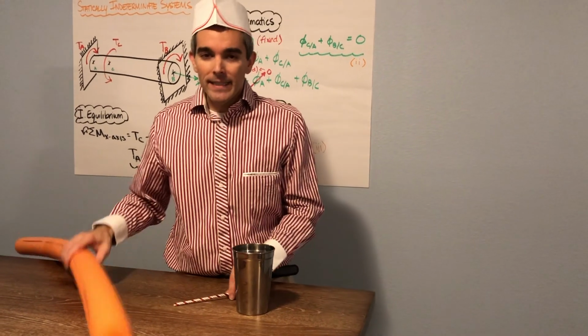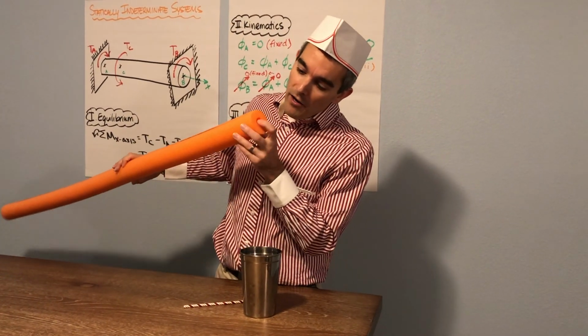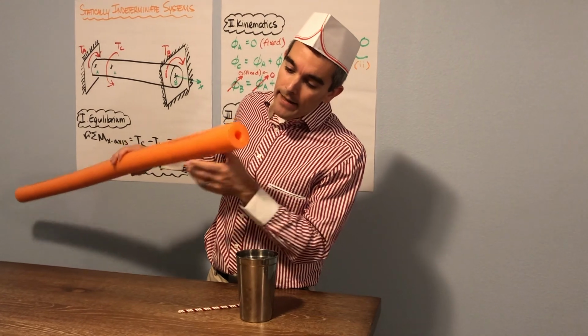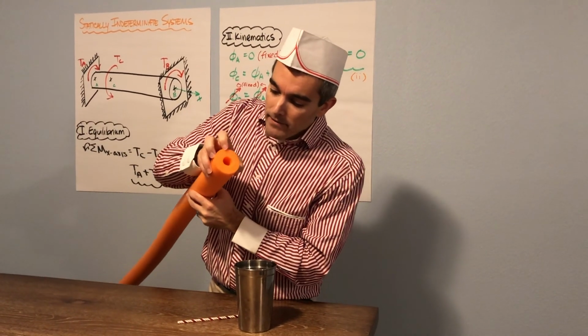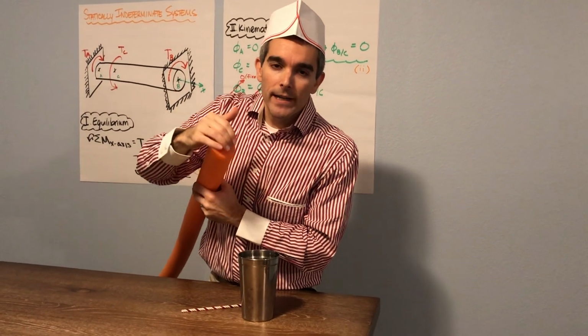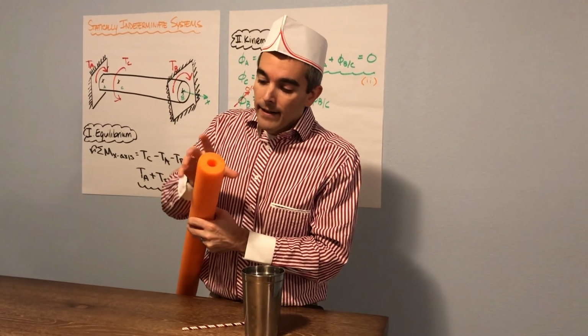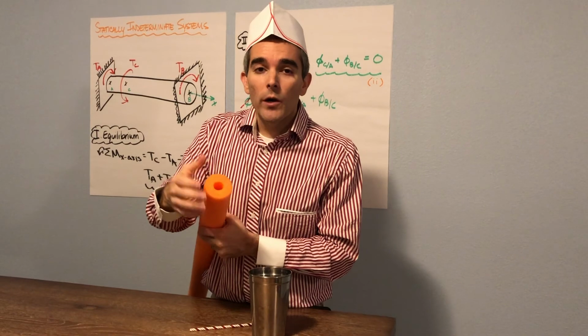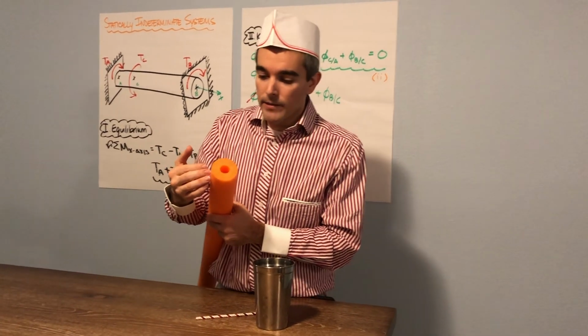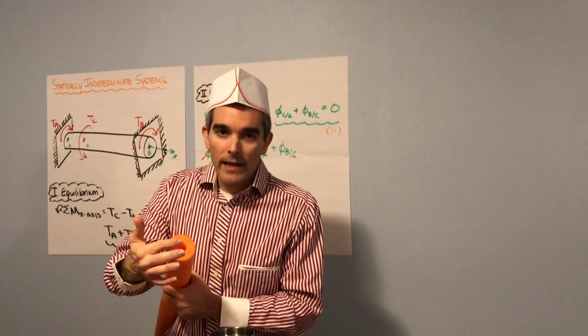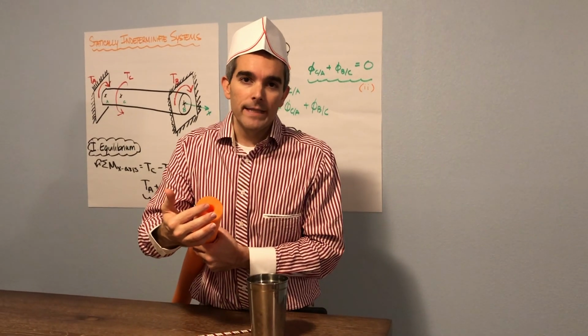So imagine just taking like our noodle or our straw and then filling in the inside. So maybe having like a steel outer core and an aluminum or brass inner core or something like that. And then when we apply a torque, the torque would be shared between the materials, but we would know that their angle of twist at one location would be the same.